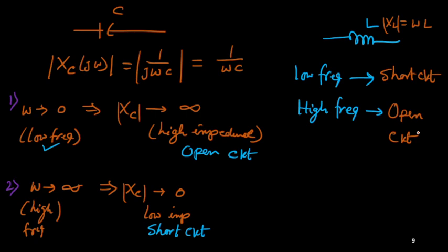So to understand a circuit, whether it is a low pass, high pass, or band pass, I will try with two signals. One time I will consider a very low frequency signal and check whether the output is available or not. Like this one, just check these things. Suppose I want to understand this circuit quickly, this is R and C.